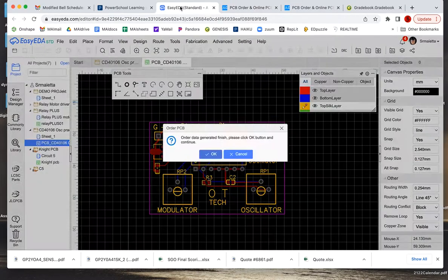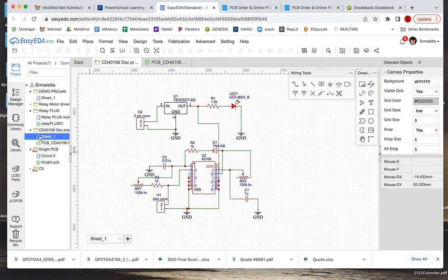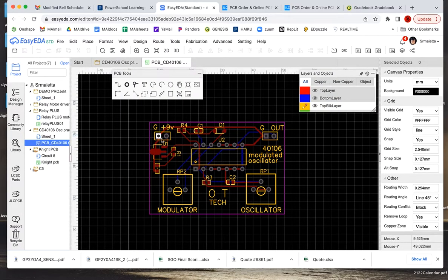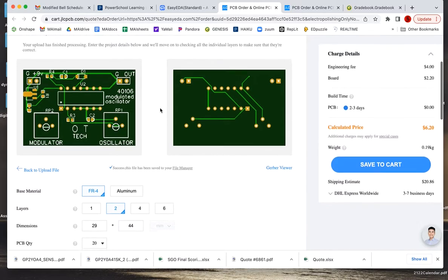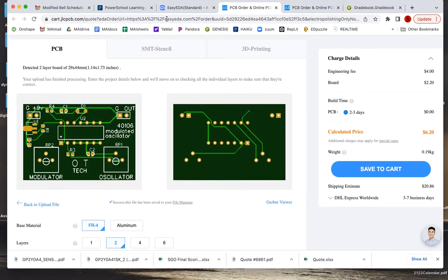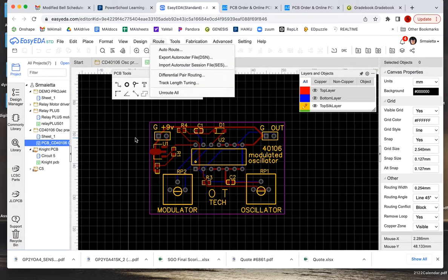So really cool process. We start by creating a schematic from all of these parts. Parts come from the library. Then we import that schematic onto a board where we arrange the parts and set all the traces, top and bottom layer. And then we can actually get the boards made and in our hand in 1 week. Super awesome. So guys, that's the overview.